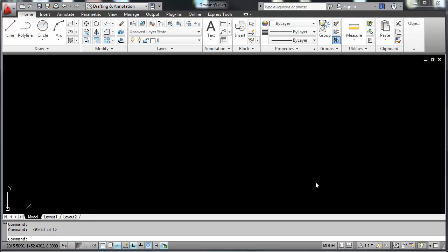This is the introduction to AutoCAD templates. First off, there's some things that need to be understood. You need to make sure that you pay attention to what units your work is going to be in. If you need to be drawing in the European standard, which is metric, and you start an imperial or an American template, you cannot switch back and forth between metric and imperial once you're inside. So you have to make sure and pay attention to your units that you need to start with.